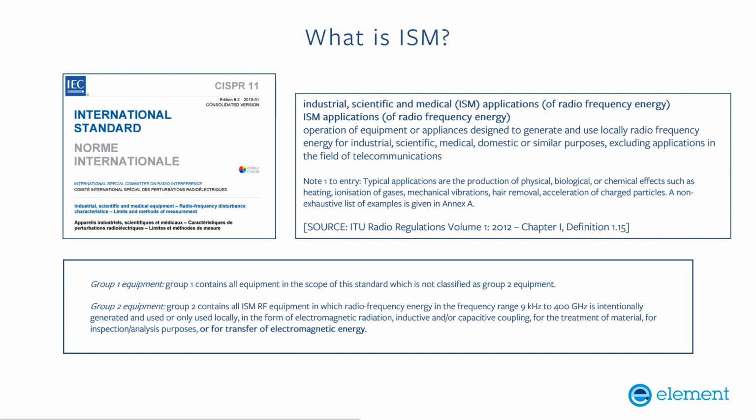In the case of ISM, I'll get more into the detail of this a little bit later on, but in the case of ISM, there is an international standard called CISPR 11. First of all, CISPR is a special committee within the IEC that deals with and provides test methods and limits to protect radio services relating to ISM equipment.